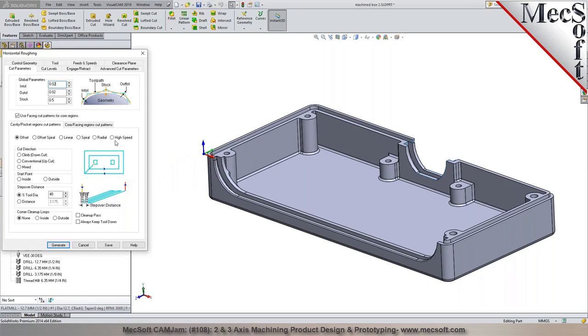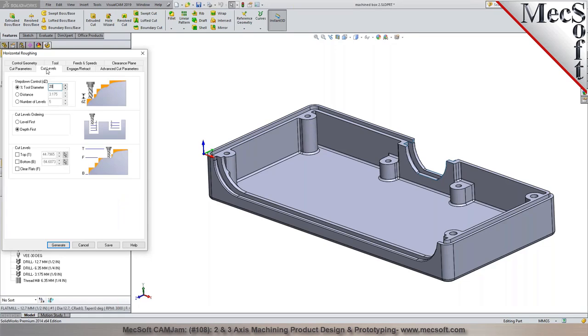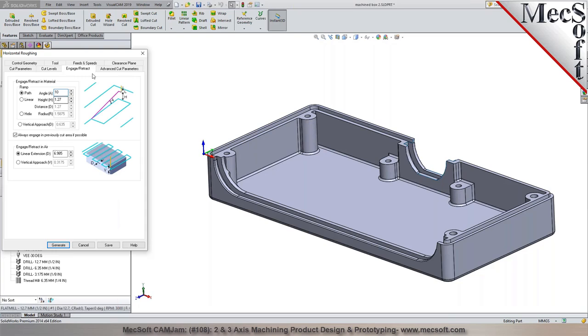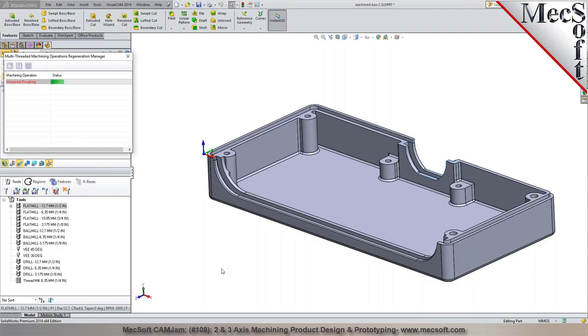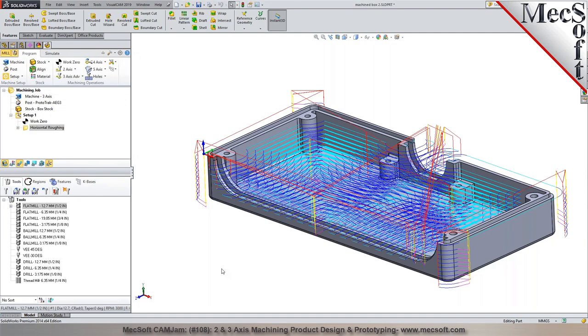Okay. Yeah. So you can program this using a 3-axis roughing operation in here, and I can specify all these cutting conditions that you're looking at right there, and then pick generate. So in this particular process, it's going to look at the part and the stock and automatically compute the toolpaths. Any questions while the toolpath is being generated? No.